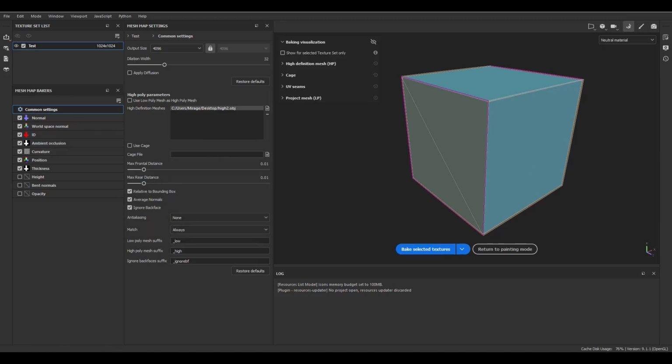Anti-aliasing can help us increase the quality of the mesh maps, especially when we have a diagonal line like this, because at the end we are going to record all the data into the pixel. And when we have a diagonal line on this UV on the pixel, we have some jaggy effect. So we need anti-aliasing to remove this effect and increase the quality.